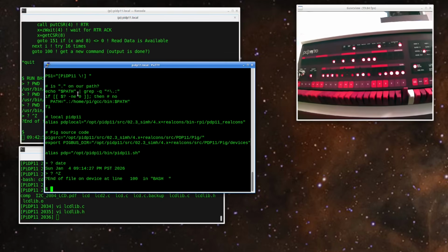And not sure where it's going from here. I spent a while playing around with a cassette tape recorder and trying to make a system for storing and retrieving files using tones on a tape. I was able to get that to work using dual tone multiple frequency coding like you have for push button telephones, but very slow, a few characters per second at the most, but it worked.